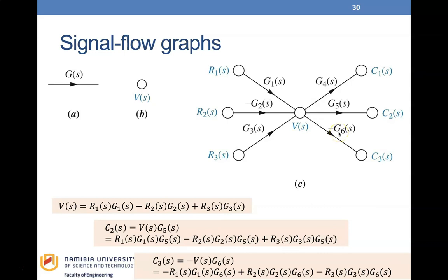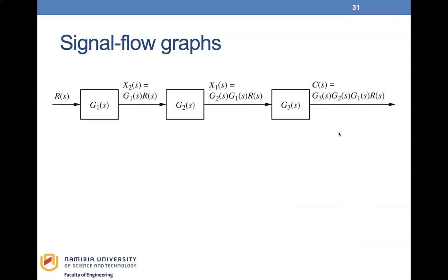In order to show how the signal flow diagrams compare with block diagrams, we will convert the cascaded, parallel, and feedback block diagrams to signal flow diagrams. Let us start with the cascaded form, which is reproduced here. The first step is to draw the signal nodes for the system. And then secondly, we interconnect the signal nodes with the system branches.